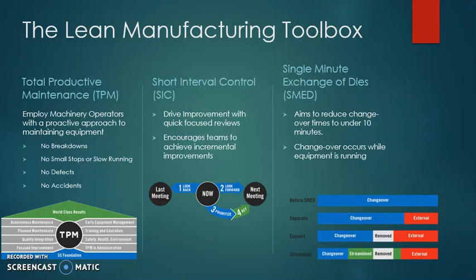And finally, SMED, or single minute exchange of dies. This concept focuses on the reduction of changeover times by either eliminating, moving, simplifying, or streamlining them. Some of the benefits of SMED include a lower manufacturing cost, smaller lot sizes, improved responsiveness to customer demand, lower inventory levels, and even smoother startups. Now let's talk about that case study.